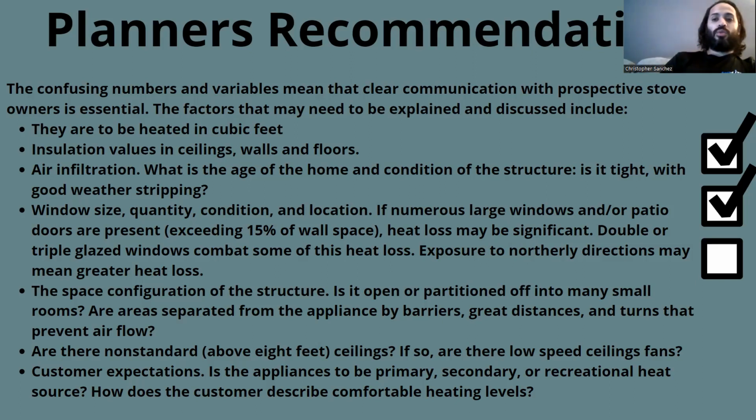Exposure to northerly directions may mean greater heat loss. What is the space configuration of the structure? Is it open or partitioned off into many small rooms? Are areas separated from the appliance by barriers, great distances, or turns that prevent airflow? Are there non-standard ceilings above 8 feet? If so, are there low-speed ceiling fans? Customer expectation: is the appliance to be a primary, secondary, or recreational heat source? How does the customer describe comfortable heating levels?